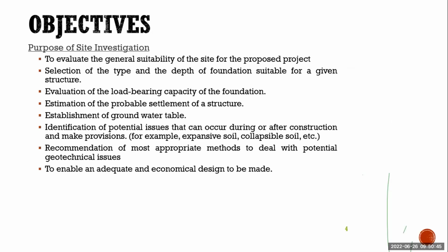Now, objectives. What is the purpose? As I just mentioned, to evaluate the suitability of the proposed project. Let us say we are going to construct any kind of structure: is that site suitable for this project or not? We can determine that based on the site investigation. Then what type of foundation can we build? It can be a shallow foundation or a deep foundation. If it is a shallow foundation, what type of foundation we are going to build, and at what depth, we can determine by the site investigation.